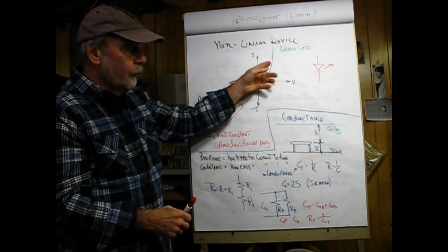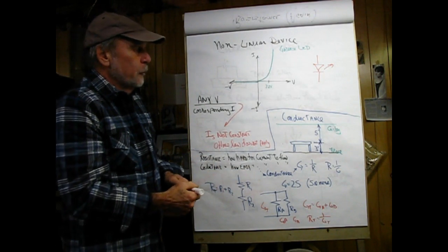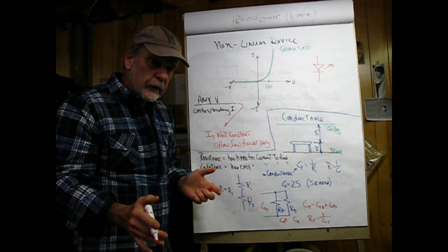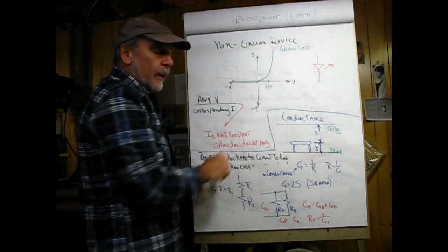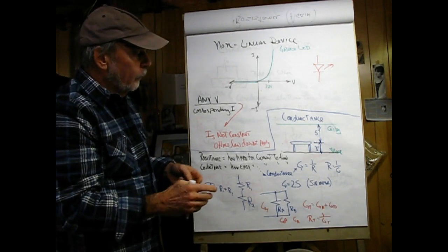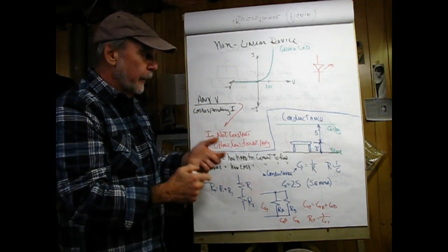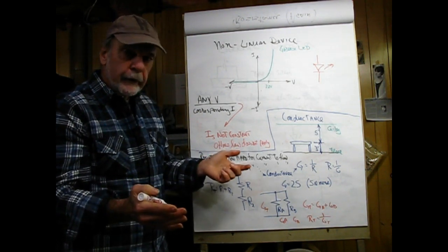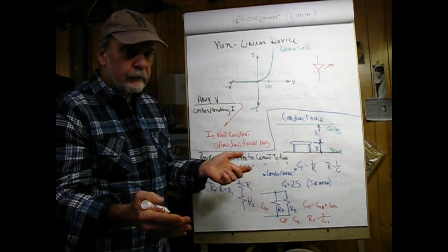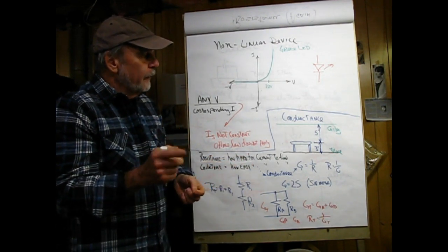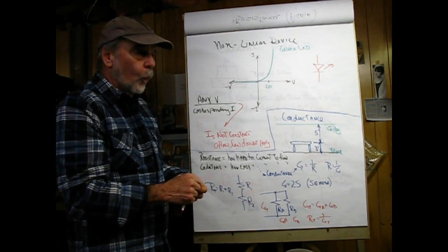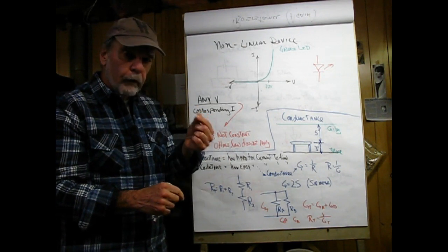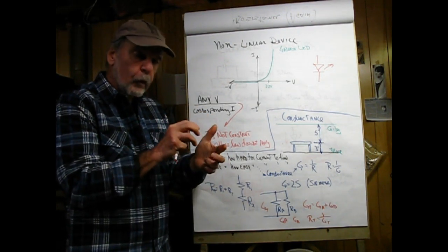Now this is governed by certain equations, and basically what this means is that the operational point, what we use when we do circuit calculations for a green LED, is about 2.2 volts. Now the same is true with red and yellow. Infrared can be 1.4 and 2.2. Why do we need infrared? We can't see it. Well, remote control television, infrared. And the different ones are blue and white. Now, white LEDs, not in a sign, in a flashlight, are blue or violet emitters that are doped with yellow emitting phosphor.